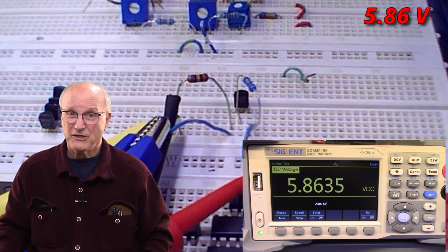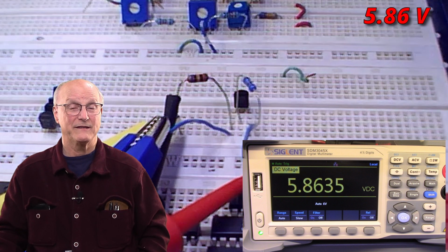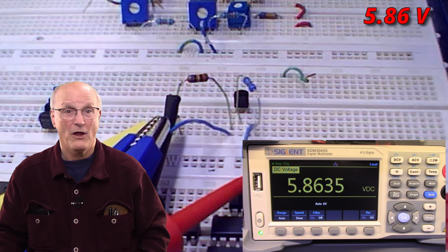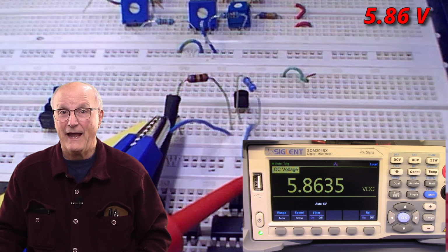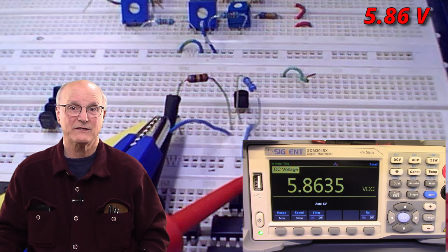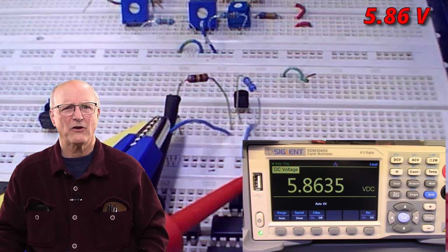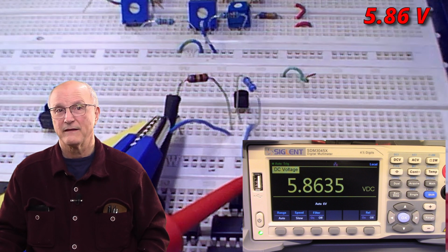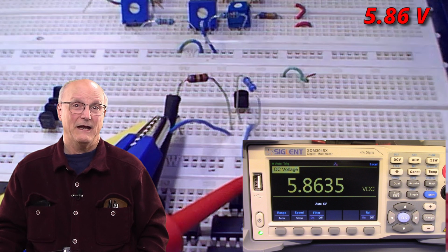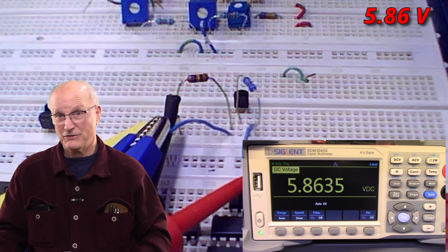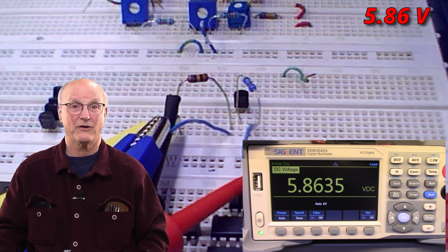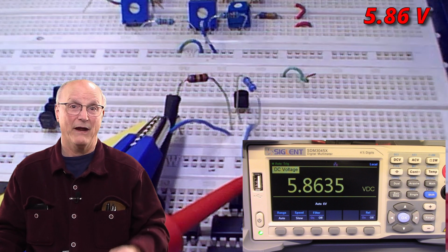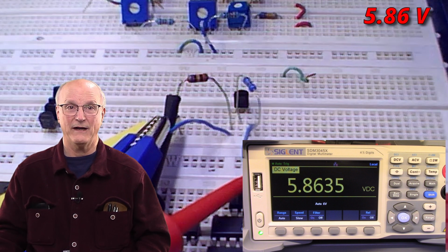The calculation of these resistor values and the success of our bench experiment all depended upon the actual real-world transistor having a DC current gain of 200. In our case, I just happened to choose a transistor that had a DC current gain of around 200 in my random pick from my junk box.